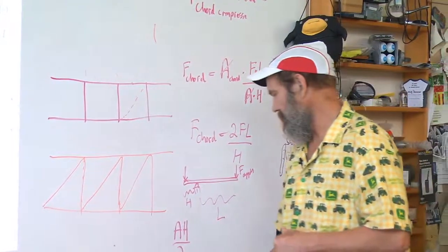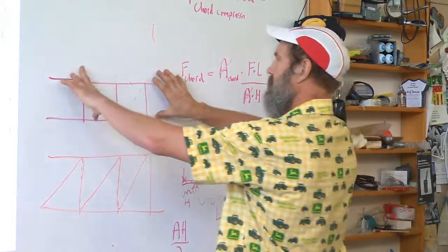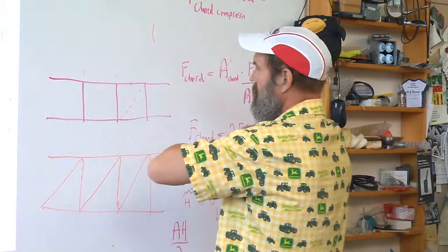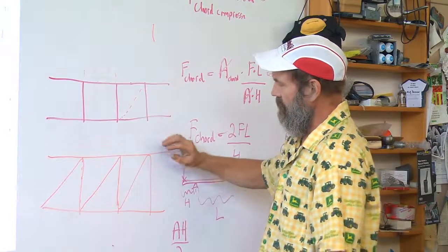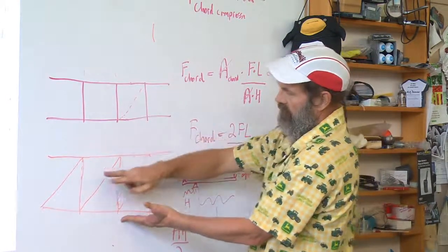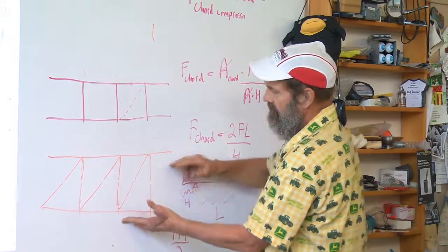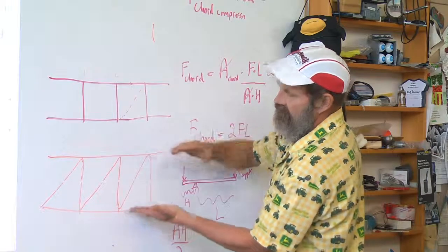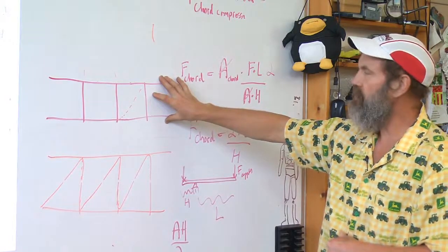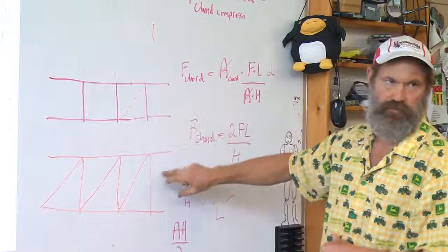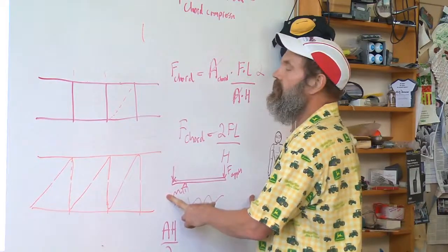Well, it turns out that if you go ahead and build one of these, you'll find that it really has no stiffness. You have to have the diagonal bracing in for the flow of forces to transfer. So what happens is you effectively have a shear through the middle of this plane here, and it allows this structure to act as if it was an I-beam. You can model this using finite element analysis and compare the two. You can also model this just using the simple straight form, closed form we did.